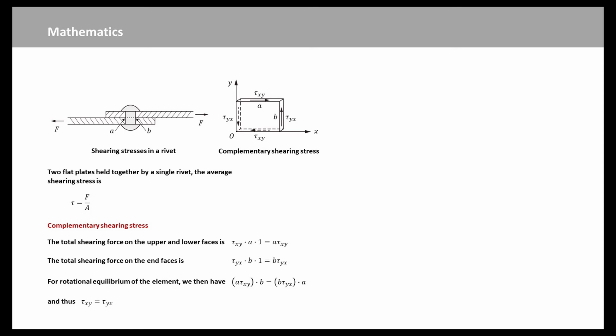The total shear force on the end faces is B times tau yx. For rotational equilibrium of the element, we then have A times tau xy times B equal to B times tau yx times A. Then we obtain tau xy equal to tau yx.